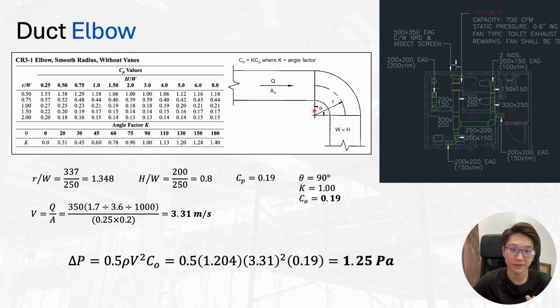If you're using a 45-degree elbow, you have to multiply by 0.6, basically 60%. So the loss coefficient will be lesser, so it's smoother. Again, we apply the same thing, everything goes the same, and we have the pressure drop, right? Let's look at another example also.